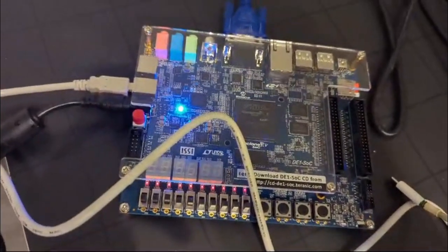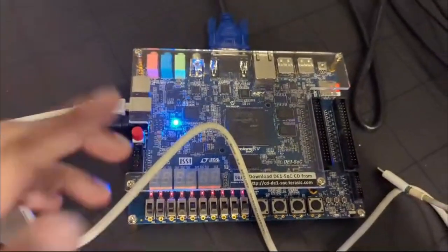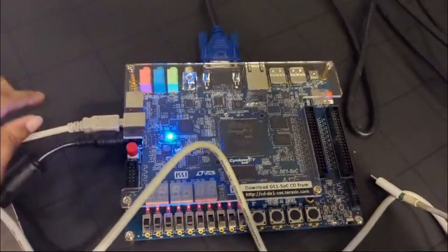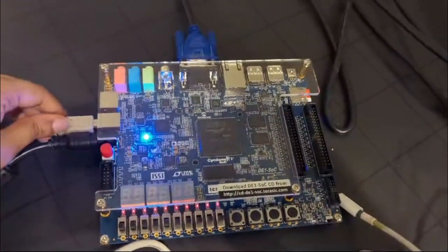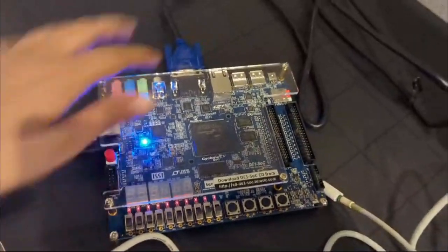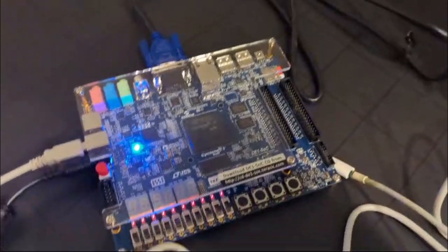Here are the connections made on the FPGA. This is the main power cable. This is a USB blaster which is connected to the laptop. And then this is the VGA cable which is connected to the monitor. Since it's prototyped successfully, this is the expected output according to our program. We get a blue box in the top left corner and there's a yellow background.